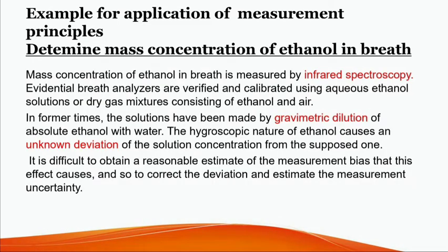An example for application of measurement principles is to determine the mass concentration of ethanol in breath, where the mass concentration of ethanol in breath is measured by infrared spectroscopy. Evidential breath analyzers are verified and calibrated using aqueous ethanol solution or dry gas mixtures consisting of ethanol and air. In former times, the solutions were made by gravimetric dilution of absolute ethanol with water.